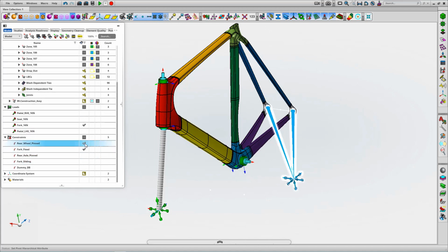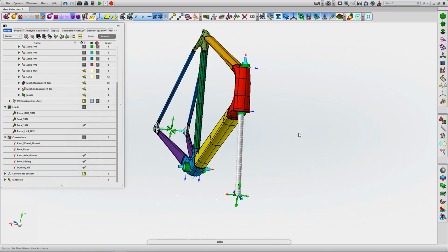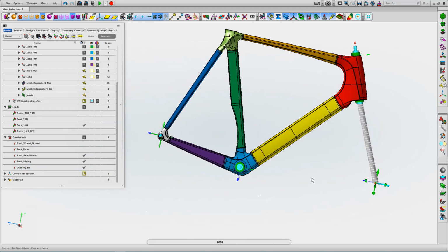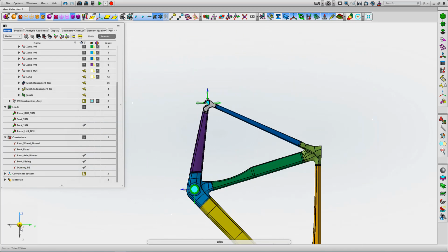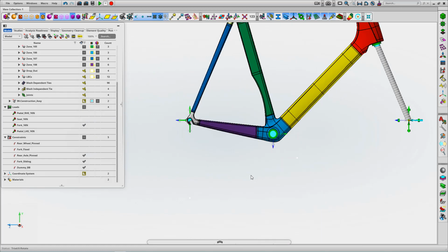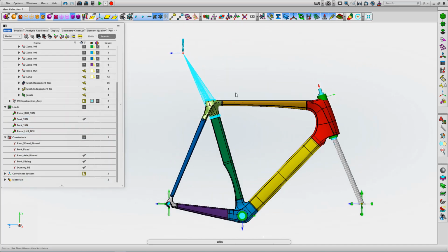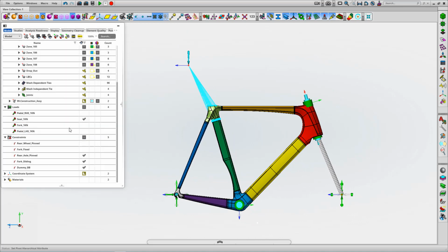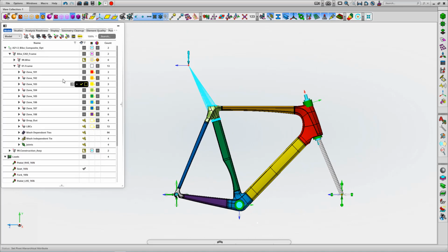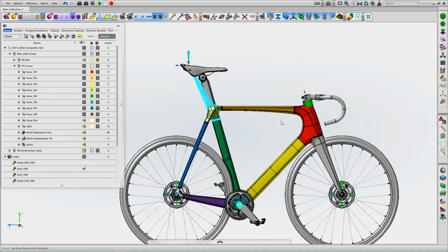So this is a load applied in a horizontal sense at the fork, and the rear axle is pinned. Okay, and we do the same again for the seat loading. And again, Apex is really useful in terms of being able to control both the loading action, the constraint action, and any rigid members which might be used to apply those loads into the structure. Okay, so again we can see that for the seat loading action in there.